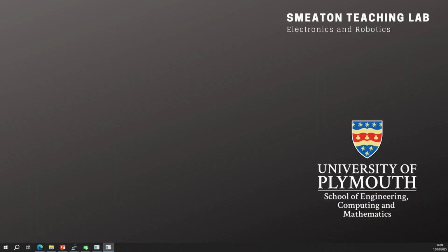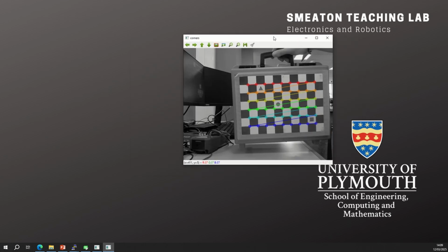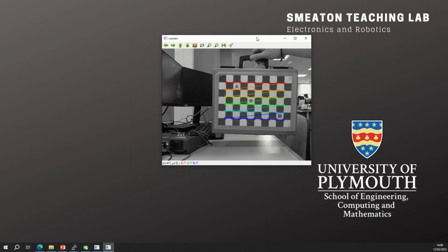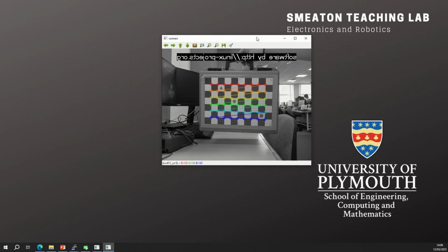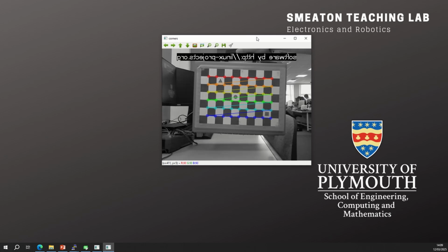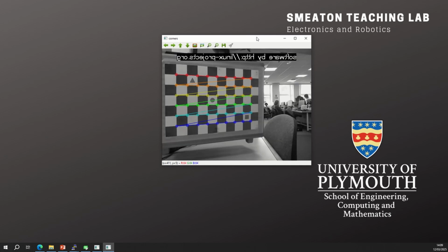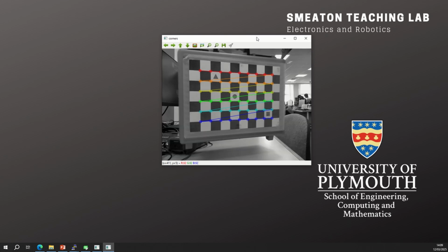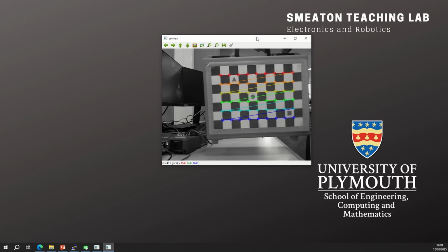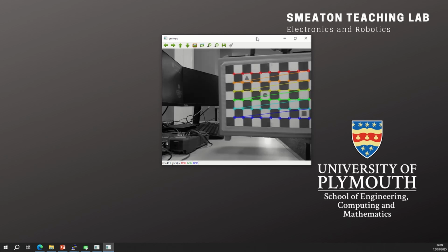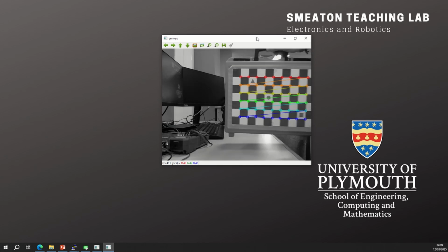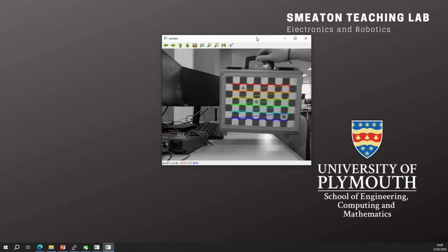As disparity mapping is very complicated, you can't just simply write code and run it and it works. You first have to run test parameters to align the cameras. As they're controlled with servo motors, they are seeing things at slightly different angles. They aren't seeing the same thing, and there are slightly different calibrations where they aren't exactly perfectly looking straight, due to standard human or mechanical error. As such, we first calibrate it.